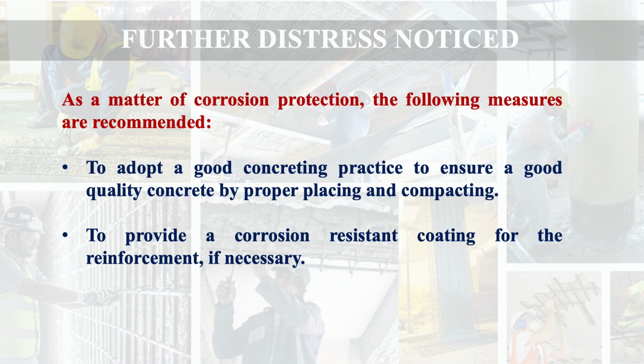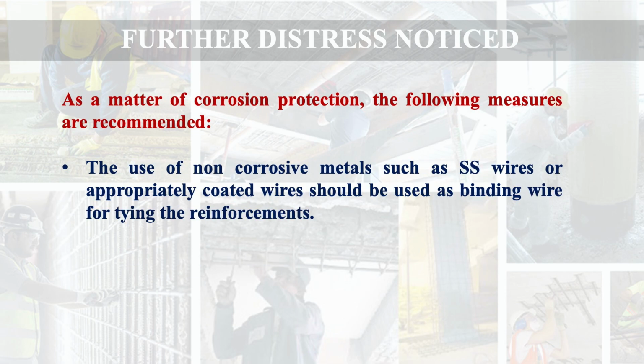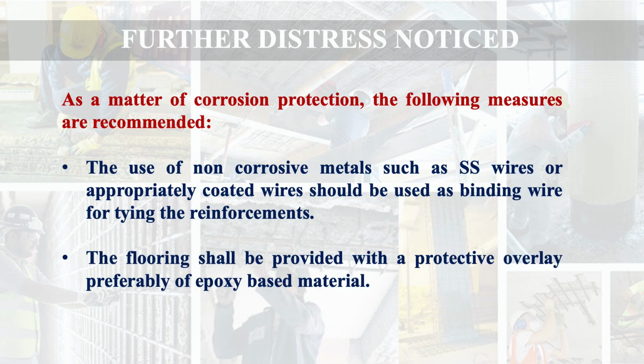Number 2, to provide a corrosion resistant coating for the reinforcement if necessary. If the environment is very aggressive, then it is recommended that the corrosion resistant coating should be applied to the reinforcement. Non-corrosive metals such as stainless steel wires or appropriately coated wires should be used as binding wire for tying the reinforcement. The flooring should be provided with a protective overlay, preferably of epoxy based material.